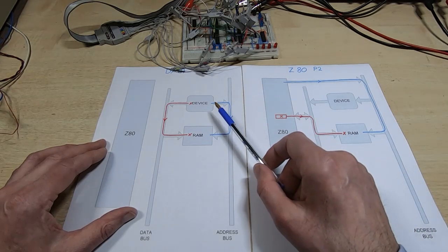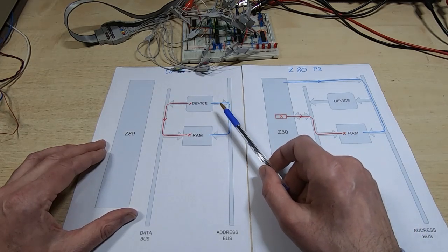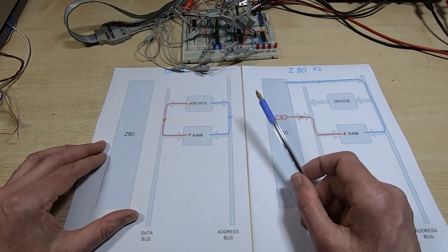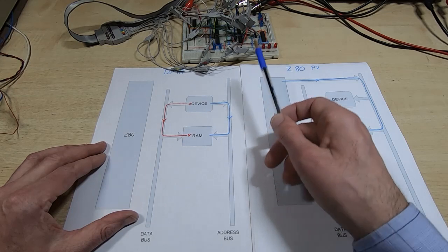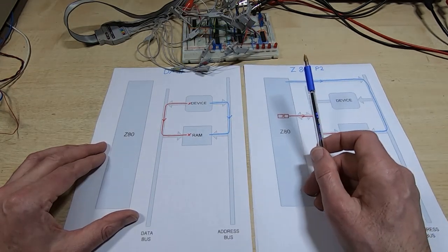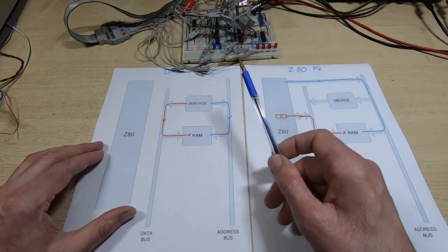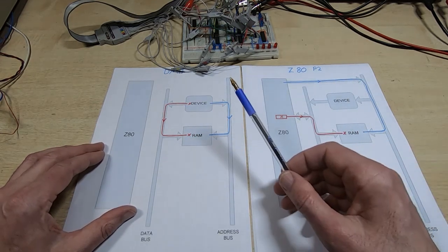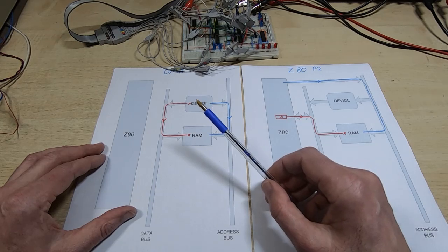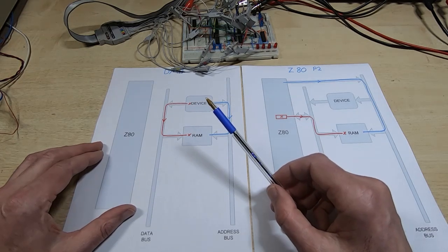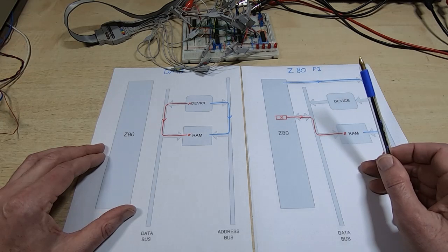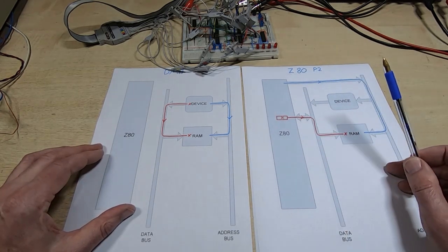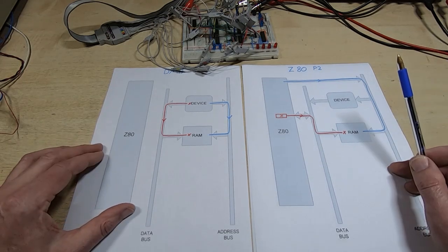I used in-out operations to access our devices because I was always intending to implement DMA, although having said that, I've already demonstrated that we can still use programmed in-out to access our floppy drive controller. The only disadvantage is that if we want to use double density formats for the disks, we have to run the board at 5 MHz, or the Z80 at 5 MHz, rather than 2.5, but that's not a big issue.